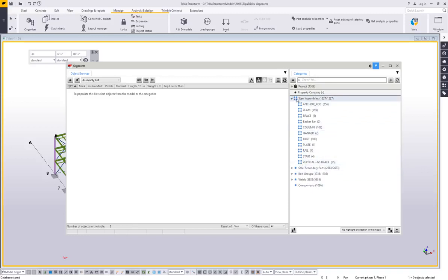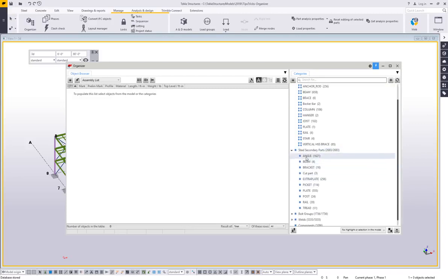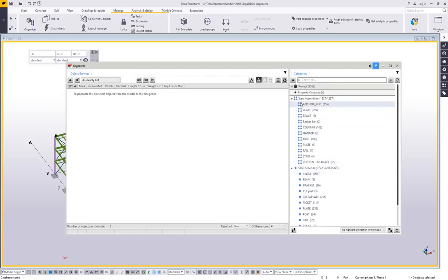You can see right away there's a little icon for the different categories. The square, the single dot, is indicating that it is grabbing part information. It's grabbing just angles, just the beam alone, no shear tabs, no clips, no nothing, plates and things like that. When you see the 4 dots, that's grabbing at the highest hierarchy level. It's grabbing it as an assembly. So this beam information is going to be the overall weldment, maybe one term that people use. So it's a completed, fully connected welded assembly, okay? So right away you can tell when one is built for one or the other.